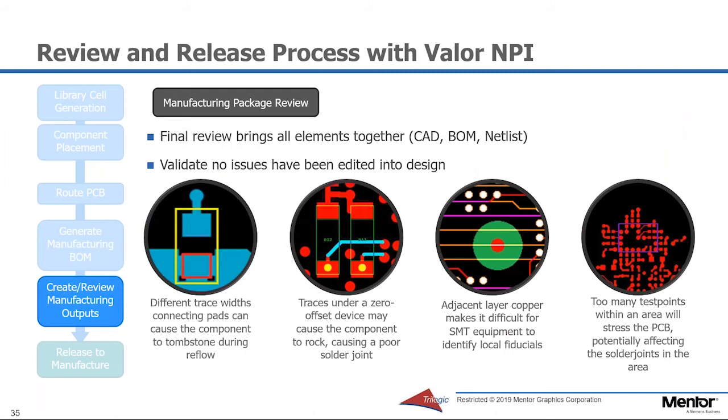The final review brings all elements together. If the DFM checks are not run until this stage, you can be spending time fixing issues that would have been identified earlier, delaying the release of the board.